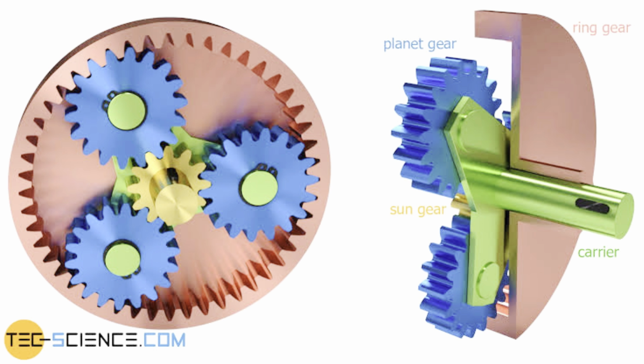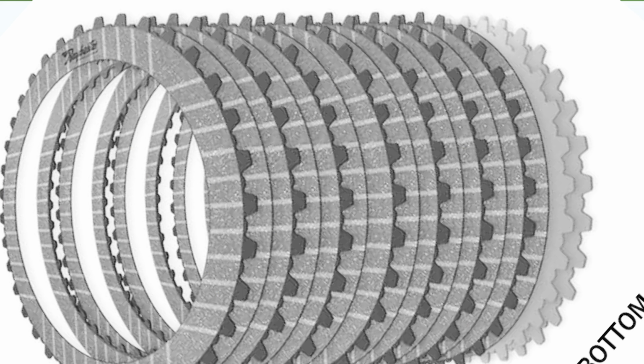The input shaft is connected to the ring gear, dark gray. The output shaft is connected to the planet carrier, light gray, which is also connected to a multi-disc clutch pack. The sun gear is connected to a drum, orange, which is also connected to the other half of the clutch pack. Surrounding the outside of the drum is a band, blue, that can be tightened around the drum when required to prevent the drum with the attached sun gear from turning. The clutch pack is used, in this instance, to lock the planet carrier with the sun gear, forcing both to turn at the same speed.